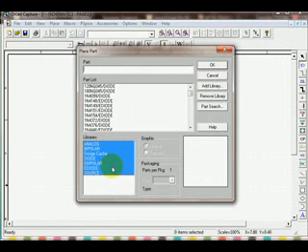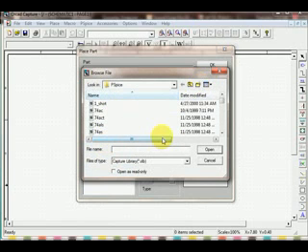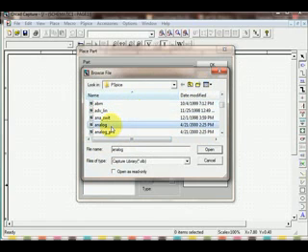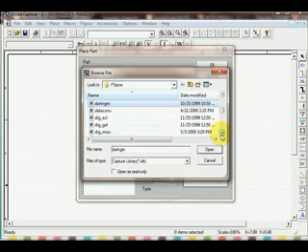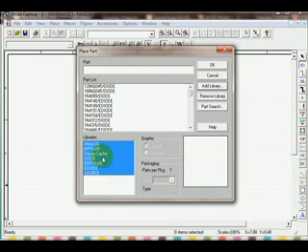These are libraries which are already added, not by default. I've added them. Now I will teach you how to add these libraries the first time you're starting OrCAD. Add library, and then you can choose different libraries by selecting first of all analog, then type A, and the analog library comes, and type S, source library, D for getting the diode library, which is here, and so on. So you can get the libraries. These are diode, bipolar, analog, E bipolar, E diode, and source. Design cache is by default, and you can select various components in these libraries.